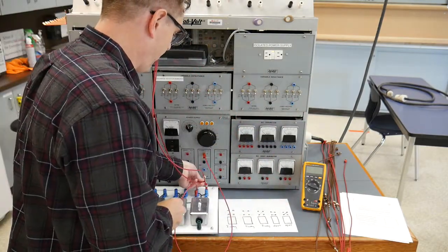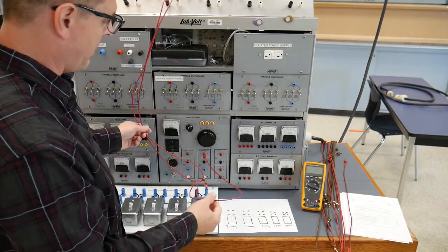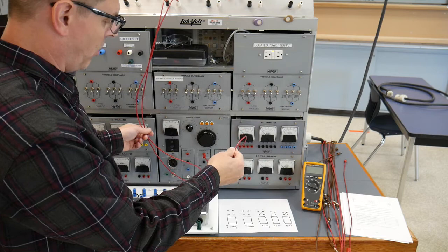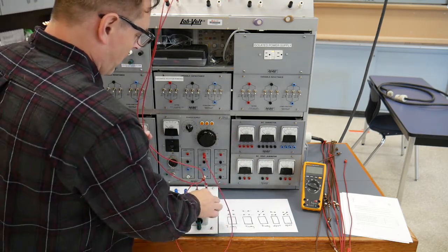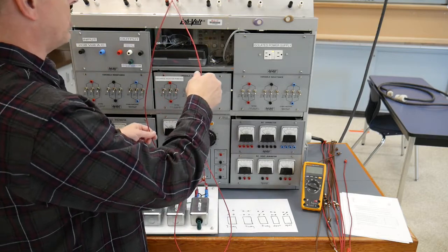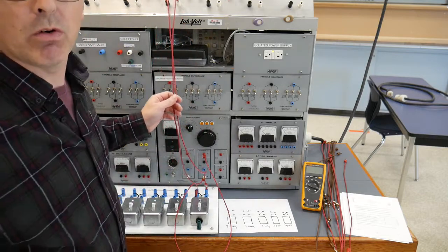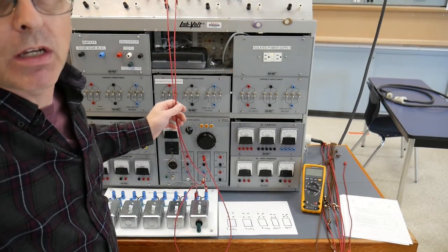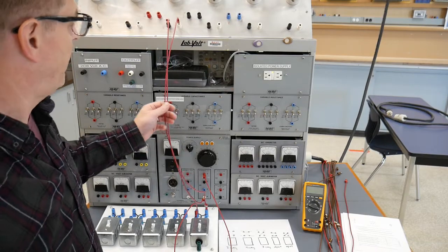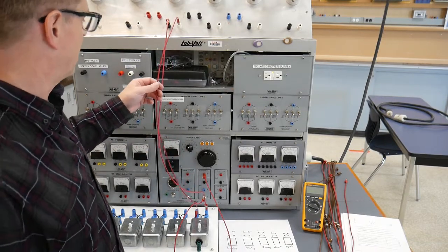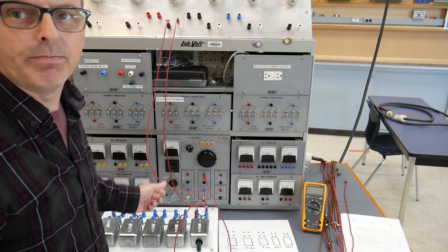Okay, so if we're looking at the actual wiring and what we name these, this is my hot, or my common, or my line 1, power coming into that switch. Through that switch, out of the switch, is now my switch leg. That's my switched conductor. Okay, and then we're going up to the light, and I'm just going to pivot the camera up just a little bit so you can maybe see the light too. You'll know when it comes on because it'll be a bit brighter. All right, and then we return back to our neutral.